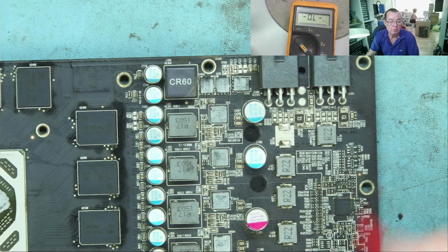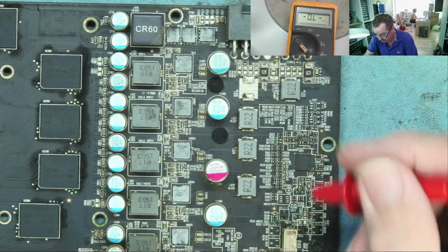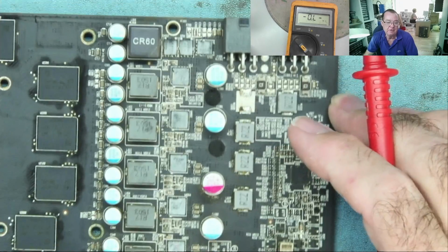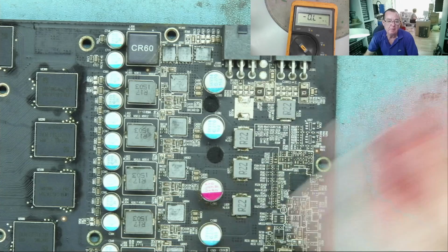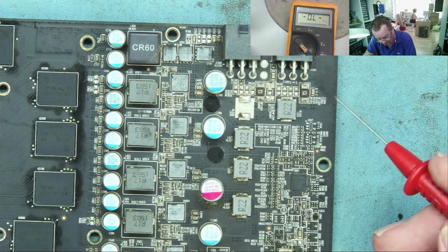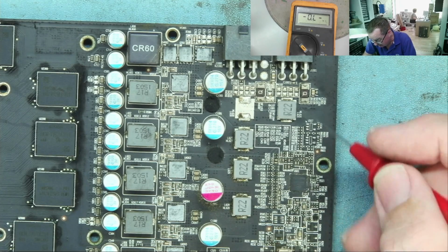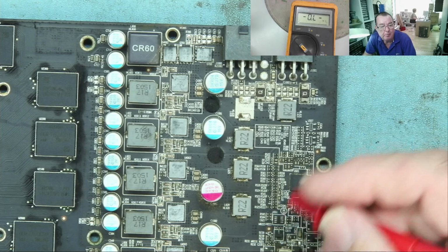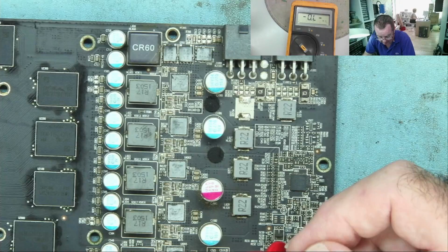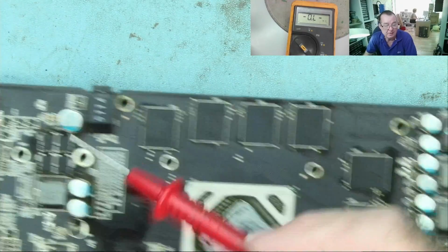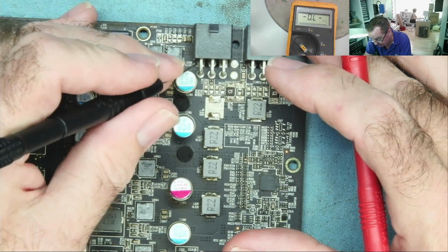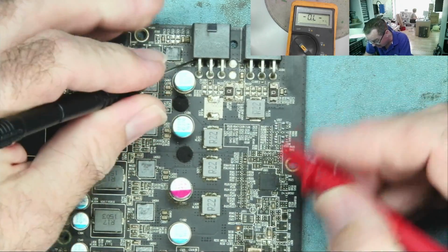We have a few more coils over here. The one on the back that read 122, I wouldn't be surprised that's the 1.8. But again, we have to measure voltages. At the moment, we can just get a general layout of what we've got. This will vary from graphics card to graphics card, but you're looking for the same sort of things. So these here are probably filters. The reason I say that is because there's none of these driver chips or these MOSFETs next to them. If they're filters, they're probably on the voltage rail coming in, which I think on here is down under here.